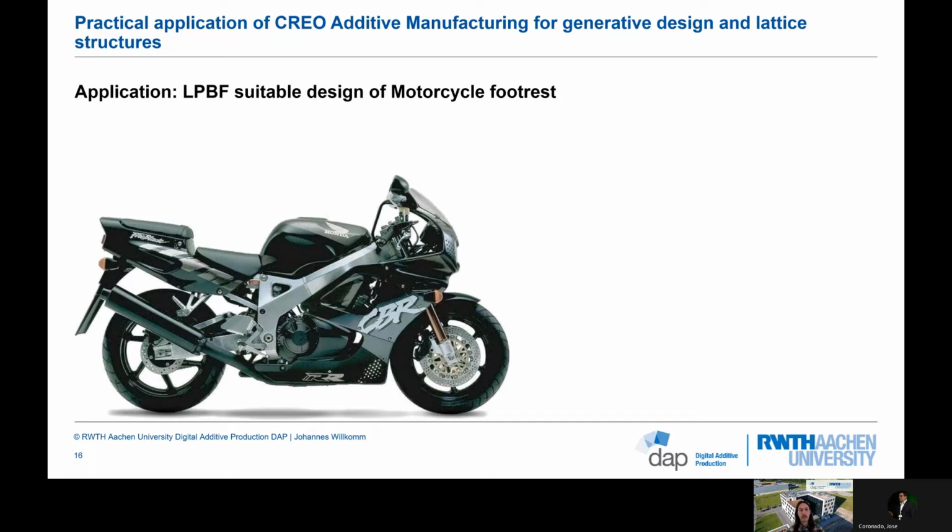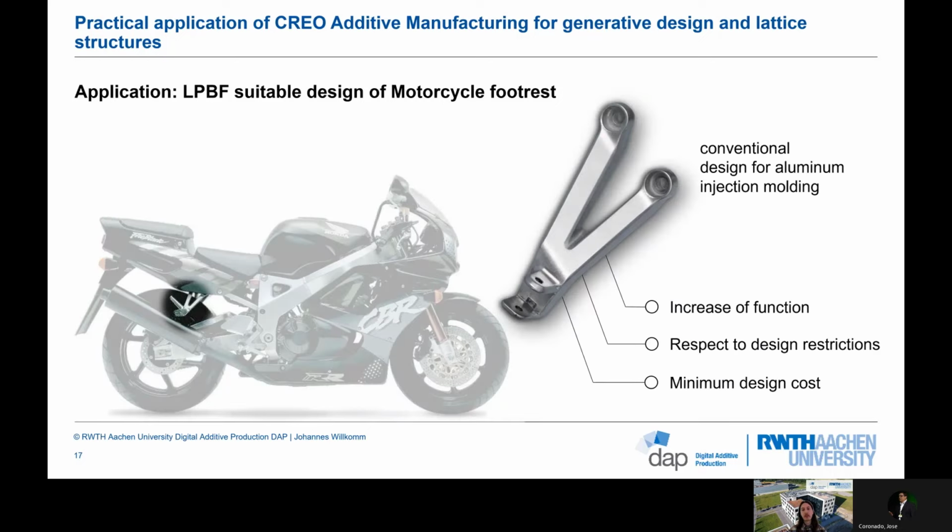In this project, we chose a motorcycle, a Honda Fireblade, which you can see here, and there we chose the footrest as a demonstrator. Conventionally, the part is manufactured by injection molding, and we want to use LPBF to increase the function of the footrest by using generative design and lattice structures, which are both integrated into Creo Additive.